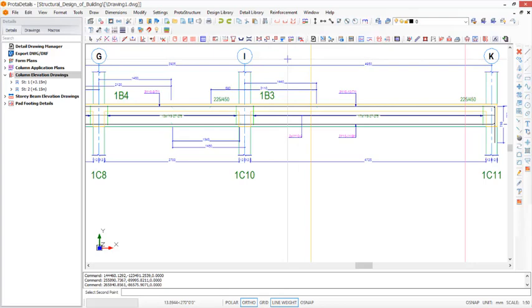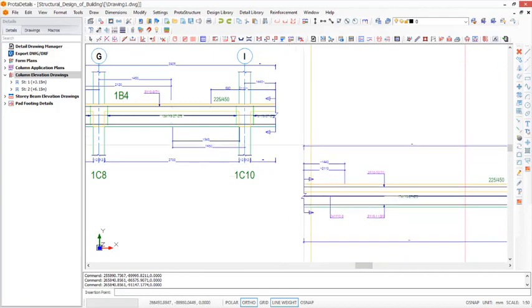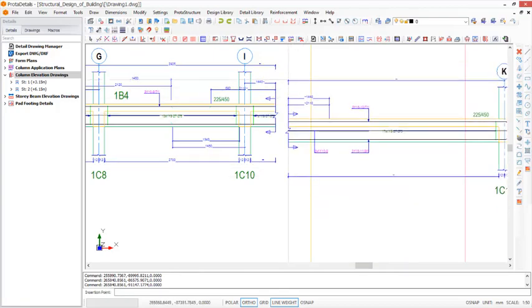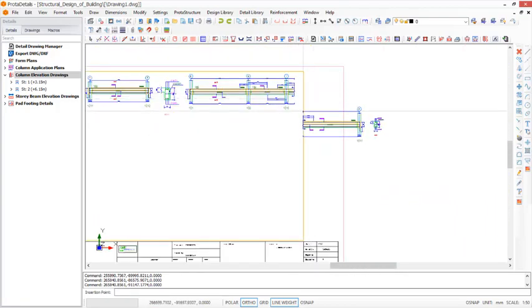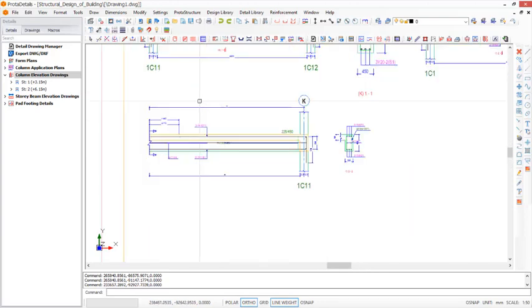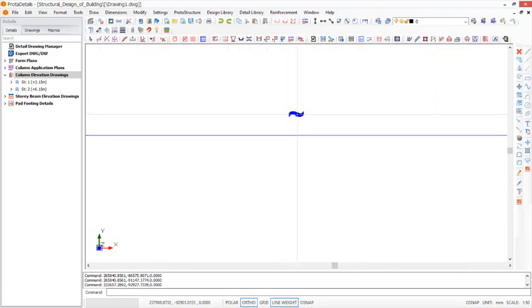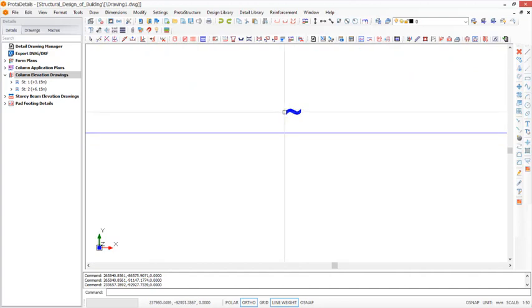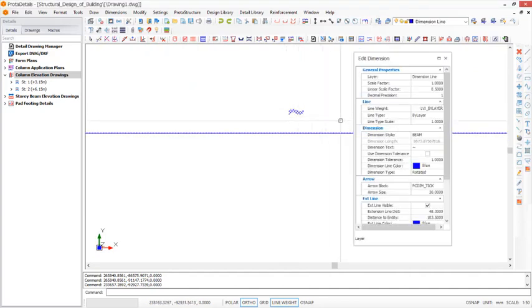We want to crop it from this provision, this point. Just click right there and then move your hand downward and click. So this is going to cut this. You can see the way it's being cut. All right, so you take it all the way to these provisions and then you place it here. Now we proceed. If you check very well on the dimension, since you took note of it, it has automatically disorganized this dimension. So you just have to double click on that.